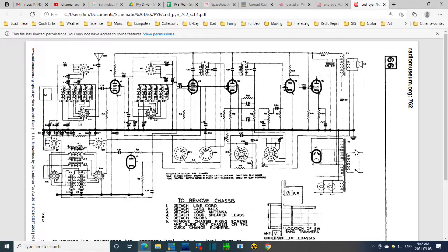The 3-section capacitor is only using, you know what, maybe it's using the same section all the time for the oscillator. Let's figure that out. So these are the oscillator coils, and there has to be one of those 3 big capacitors operating against these coils, in parallel with these coils. See, these wires, they actually don't go anywhere. This one does. This one, hey, from the grid, and then selecting a coil, and then selecting a capacitor.